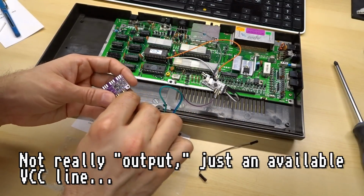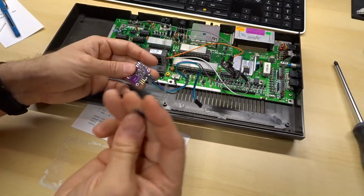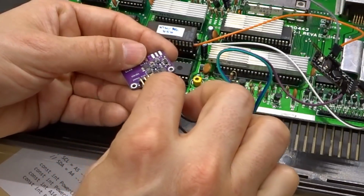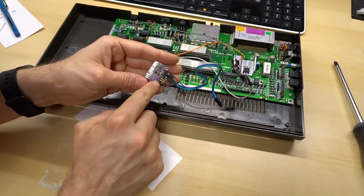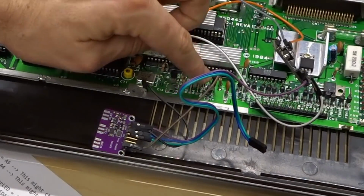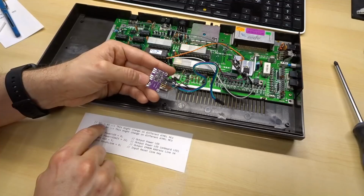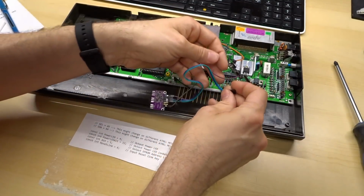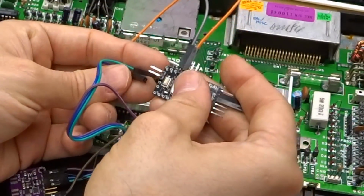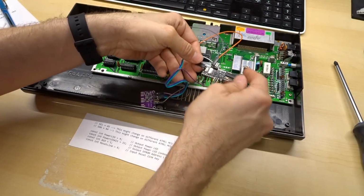Let's use this black wire here to plug into the ground on the motherboard. So that's going to go right there. And we're going to use this brown wire as the clock output, so output 0. So this brown wire for clock 0 goes onto that pin header on the motherboard, so that's feeding the TED directly. Okay, so SCL is this green or sort of turquoise wire. SCL is A5. So turquoise wire goes to A5, which I think I have to look at the bottom of the board. That's A5. This one next to it is going to be the SDA line.